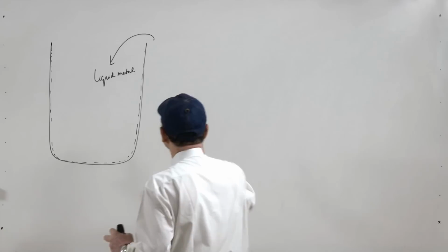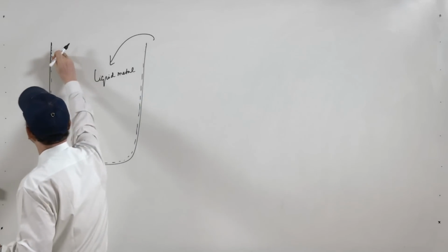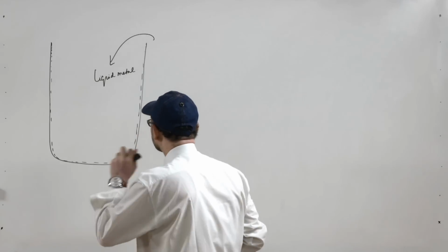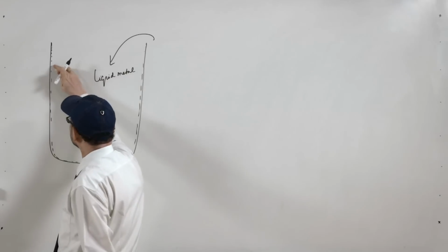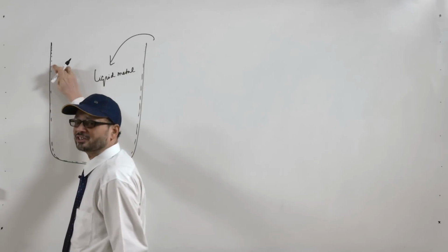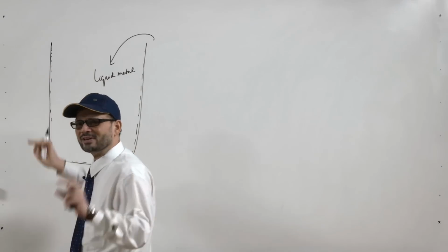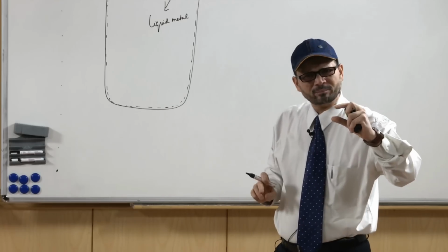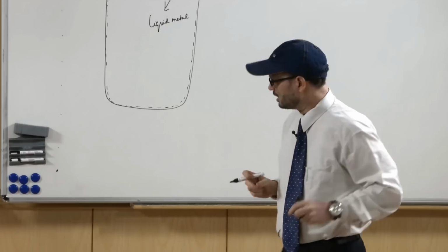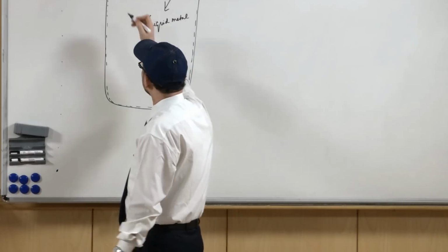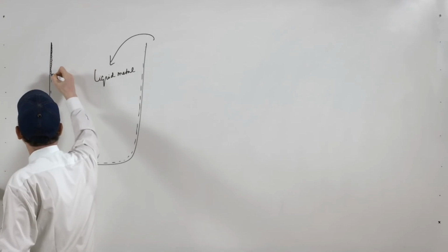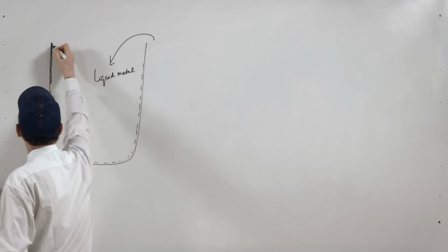So, there will be crystallization of solid particles, solid phases. Since the heat transfer rate is maximum here, and we have also understood that with a larger degree of undercooling the nucleation rate is maximum, you have formation of very small nuclei at these surfaces and a skin is formed.